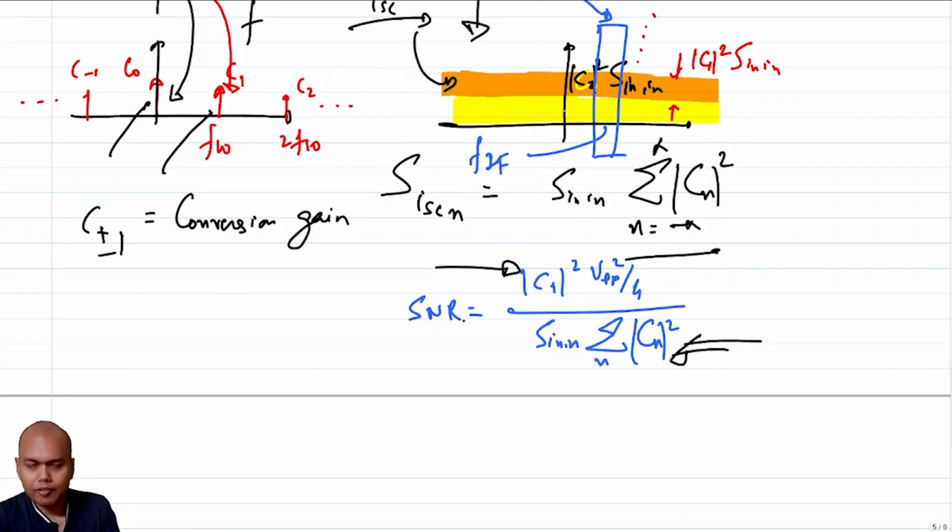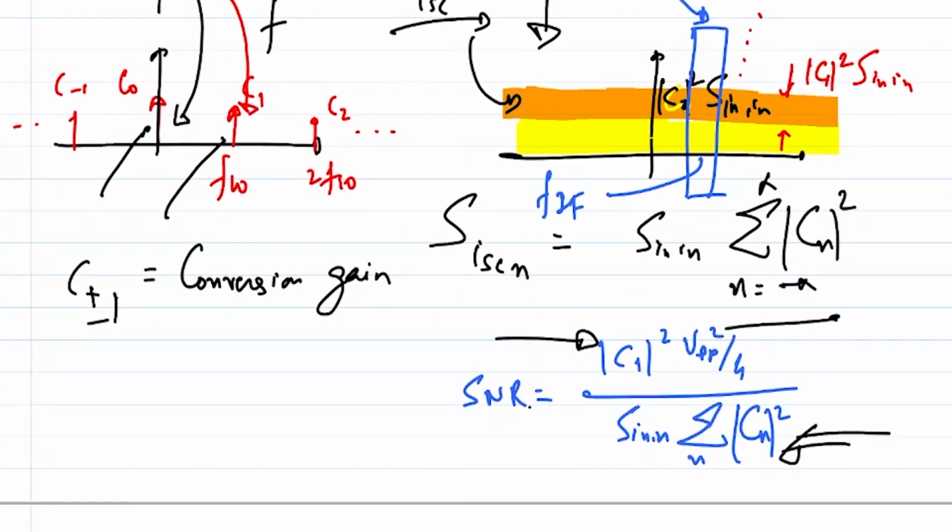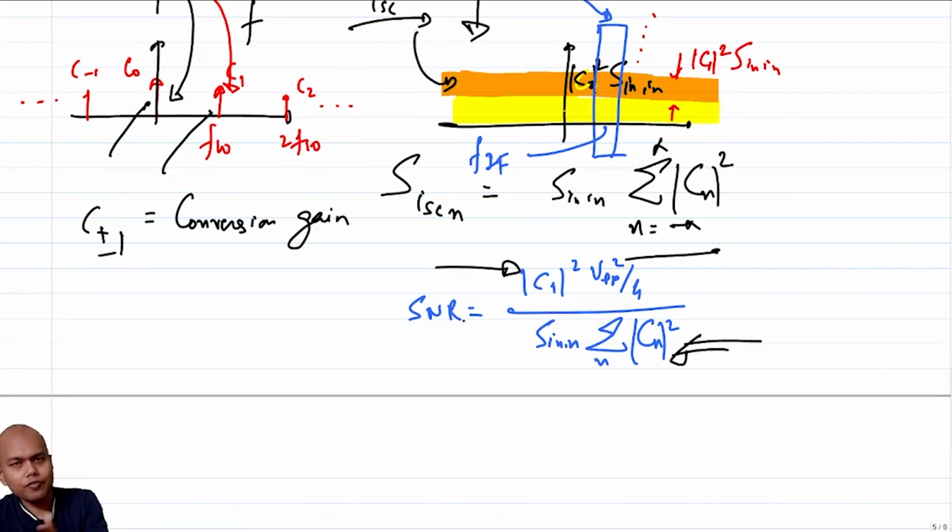When you are doing an LNA, for example, in your simulator, if you want to find out the transfer function of an LNA, you typically do an AC analysis. When you are doing the similar analysis for a mixer, you will not be able to do an AC analysis, because in an AC analysis the assumption is that there is no variation, it's an LTI system, so there is no second input. In this case, you have two inputs operating at different frequencies. Hence, you will not be able to do a simple LTI AC analysis. You will have to do a periodic steady state analysis.